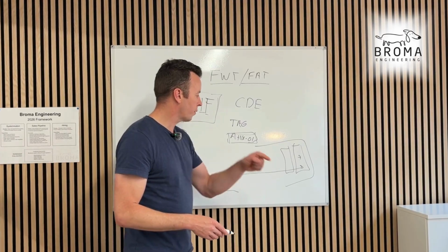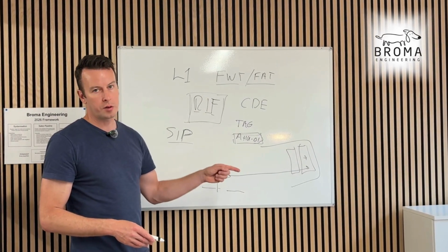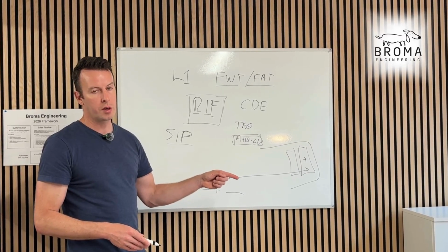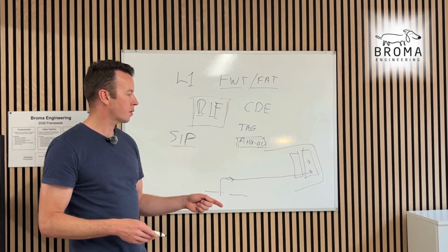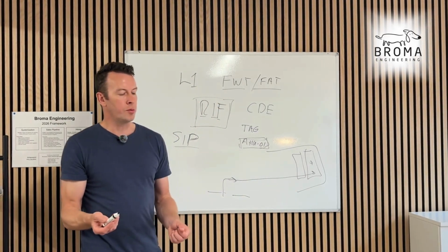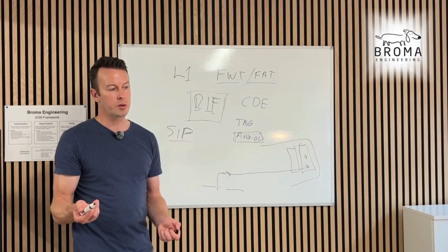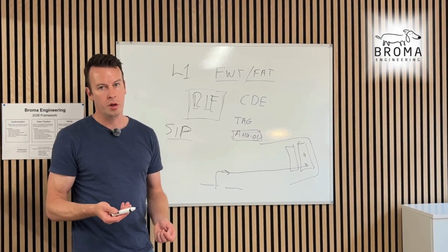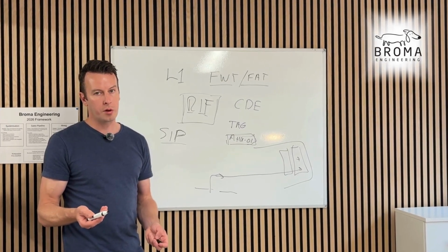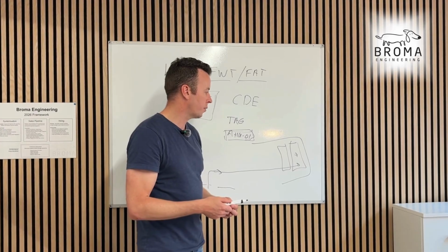But hopefully it's gone from the factory straight to the facility and straight into place. So we're not storing it outside. Sometimes there's mold inside these things, so I'd always have dehumidification inside the AHU during shipping, because when it was wrapped it might have been quite humid, and then that humidity is trapped in there for however long it takes to get to site. And if there's a delay, it might be stored outside for a few days with the wrapping on.